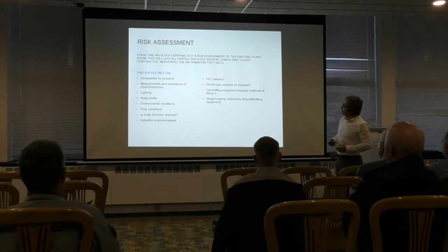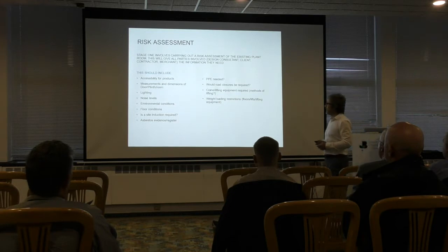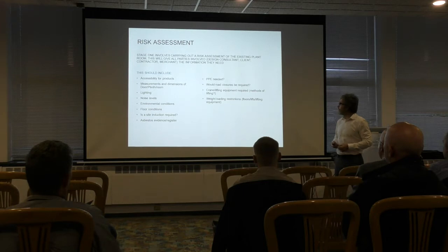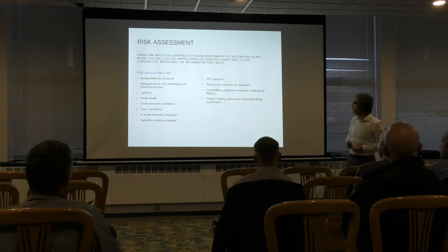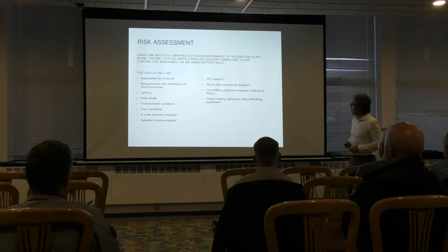Would PPE be required? You'd cover that under the site induction. Would road closures be required? If you're delivering large items of plant, the last thing you want is your large lorry coming down the road and blocking roads, and then you've got issues there. So if we need to look at road closures, again, things like that can really take time to organise. Crane lifting, obviously lifting equipment, lifting up onto maybe a rooftop plant room, but also lifting down into a basement, things to look at. And then loading restrictions as well, with floors and lifts, that kind of thing.